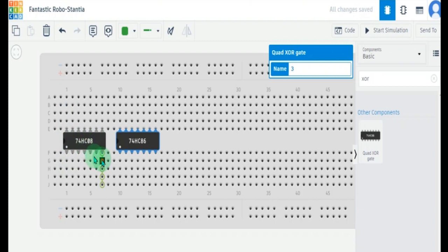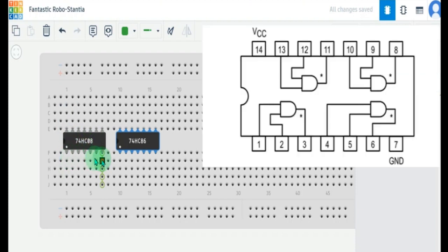So first of all, what is the internal of an IC? Let's see it. This is pin number 1, this is pin number 2. So how can we distinguish these pins? We can see there is a small cut marker here, and there is also a white point up here. If we put this point to the left, to my left, then the pin here is pin number 1, and next is pin number 2, and up to here it is pin number 7, and above that is pin number 8, and up to here is pin number 14.